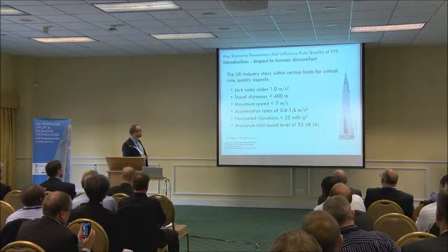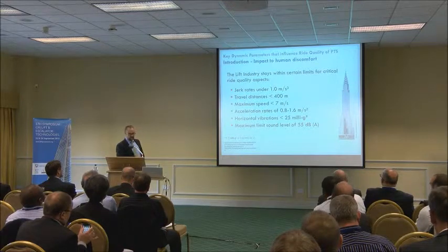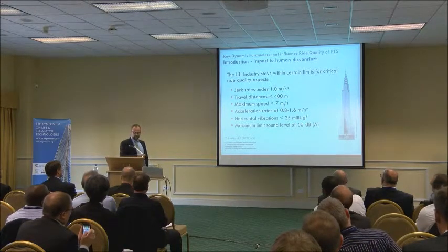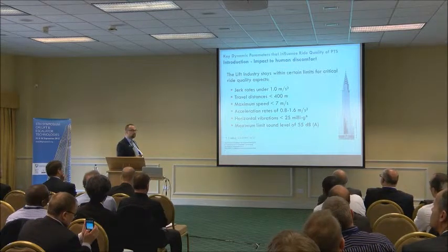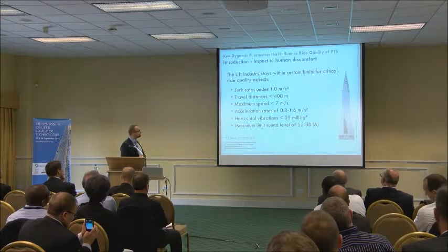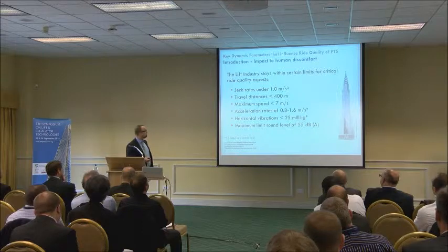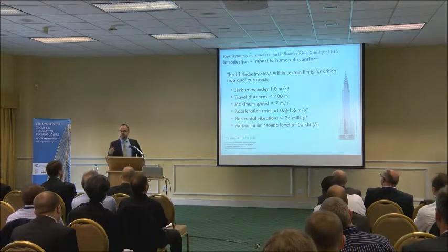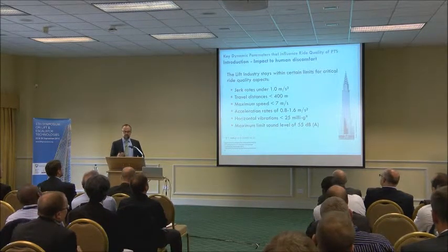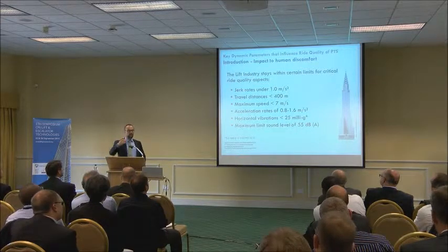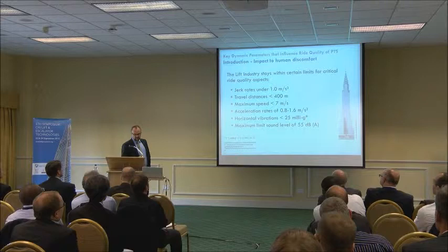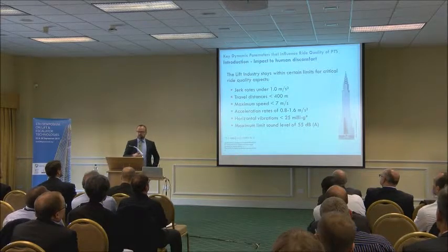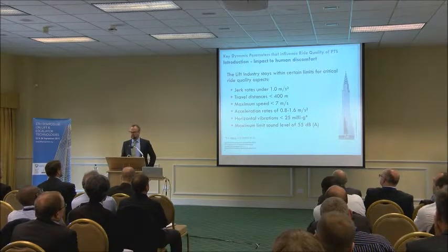If we, for example, are able to ensure jerk rates under 1.0 meter per second to the power of 3, or travel distances below 400 meters, because everything above 400 meter travel height can cause an uncomfortable feeling for the passenger.